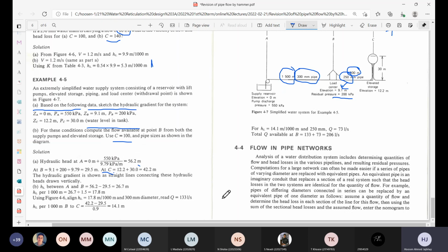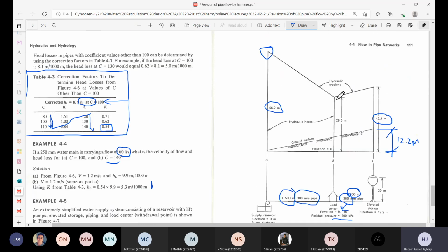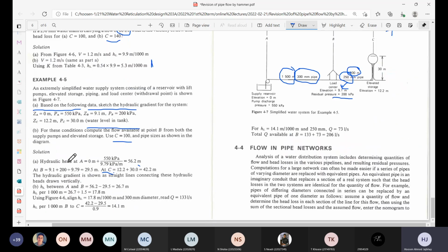So we now want the flow in pipe AB. Throughout that length of the pipeline, the diameter is not changing, and we're not adding any water in between. So for that entire length of the pipeline, the flow in liters per second would be constant. That's from your continuity equation: V is not changing, and A is not changing as the water flows between those two points. So Q would be a constant.